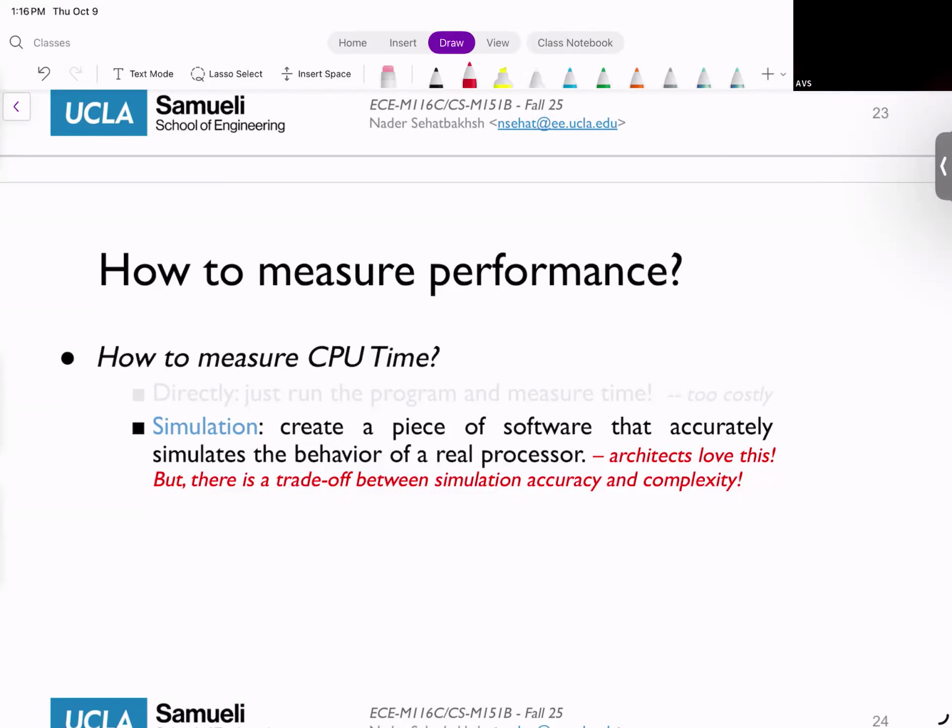So the question is, when you're moving up in the level of abstraction, you're going to lose some of the semantics. For example, at the C level, you're not going to see the parallelism that you have inherently in hardware, because things at the C level are naturally sequential, right? So yes, when you're doing your CA1, you're going to see that you're calling functions one after another, but in fact, these functions are parallel. So how do you fix those things? That would be a challenge for you guys to think about. There are tricks that you can do, but there are things that you cannot generally capture. And this is a trade-off.